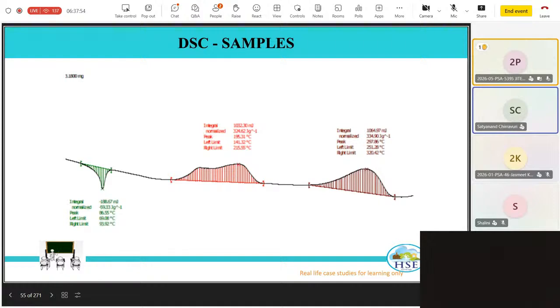If it is TMR 2, you have only 2 hours of time. Once you reach TMR 2, that means you don't have any time. Your process is running away from you. Come what may, you are going to have dangers.